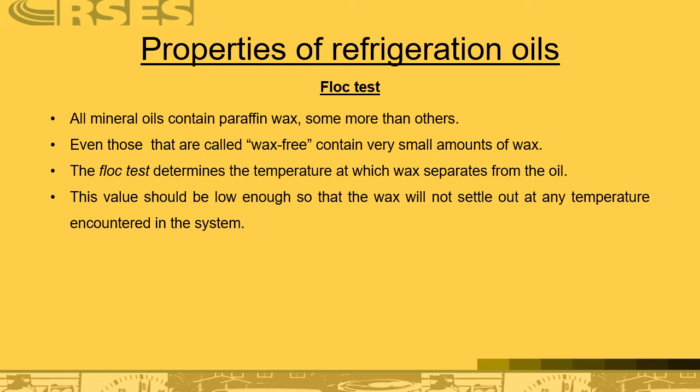Floc test. All mineral oils contain paraffin wax, some more than others. Even those that are so-called wax-free contain very small amounts of wax. The floc test determines the temperature at which the wax separates from the oil. The value should be low enough so that wax will not settle out at the temperatures encountered within the system.